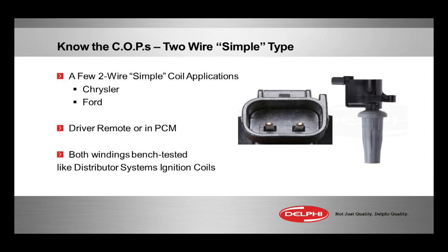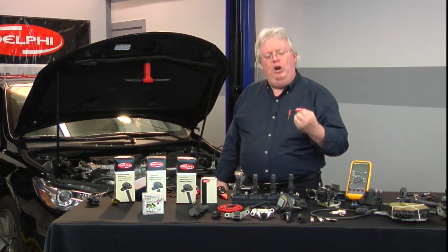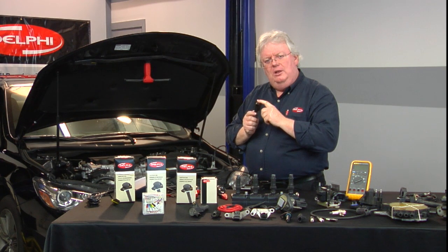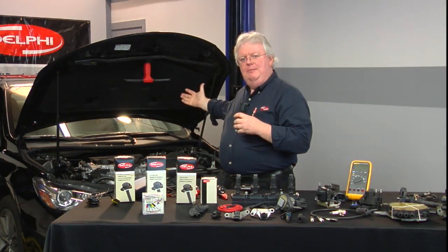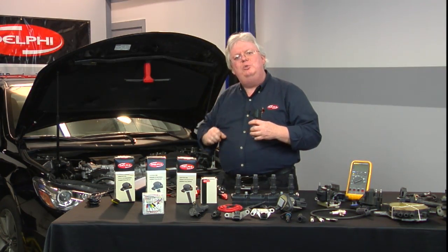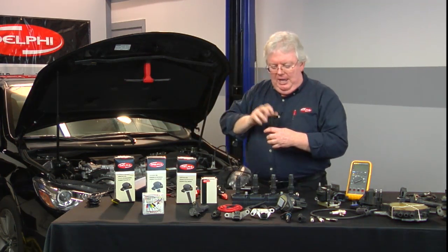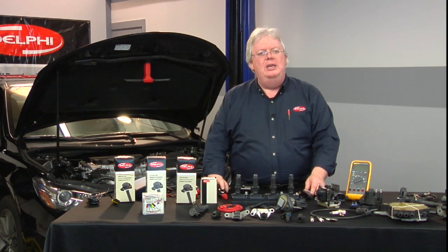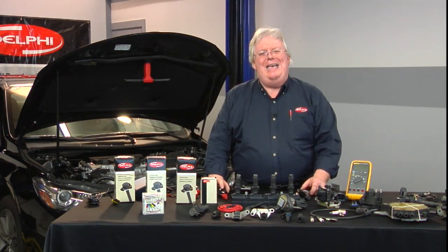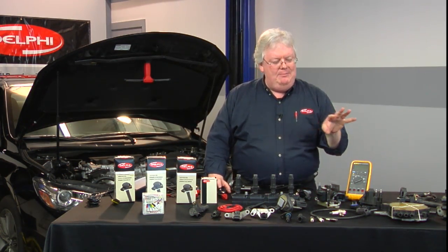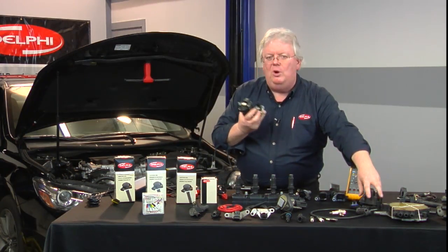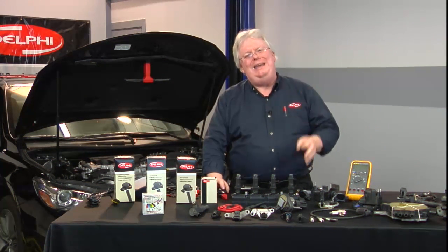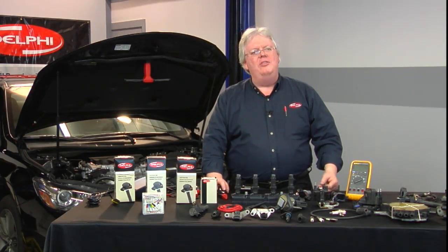That means the high energy, or I should say the high current turn-on of this 0.6 ohm load in this Ford coil is coming from the PCM, the coil driver module or ignition module, as we used to call it, mounted in the PCM, with an output for each of the 4, 6, 8, whatever coil-on-plugs. So pretty much straightforward. Bench testing we're going to look at next is the same as if you were measuring one of these or one of these. They are pretty much the same. You can check primary and secondary winding resistances with an ohmmeter on the bench.